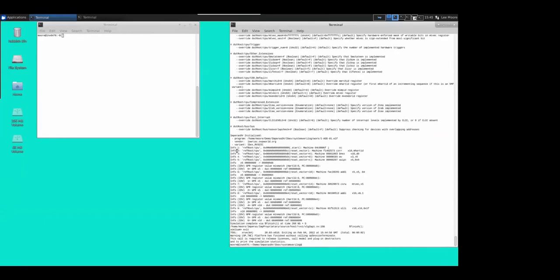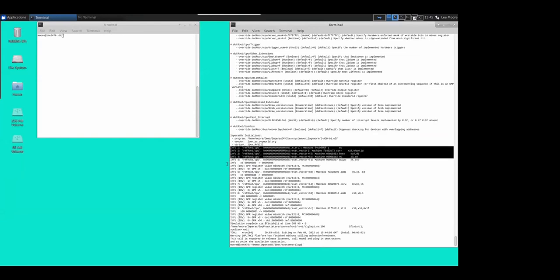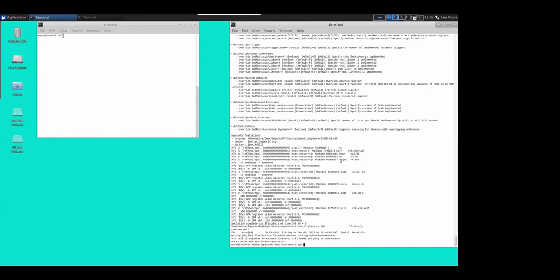So you'll see here, this is the tracing now coming from Imperas DV, and it tells us at this point we're executing an AUIPC instruction, and an AUIPC basically says add unsigned immediate to the program counter, and the unsigned immediate is 0. Therefore, we're just going to write the program counter into register X5. And yep, great, it tells us we've got D8 in the register X5. Unfortunately, the RTL tells us that it has 0, and this is why we had that difference at that point.